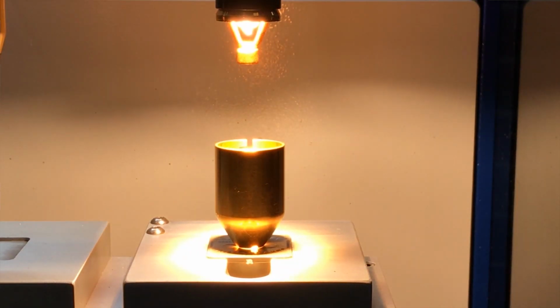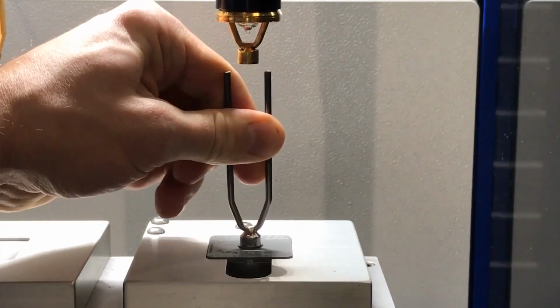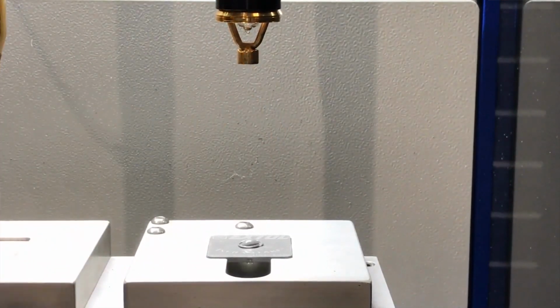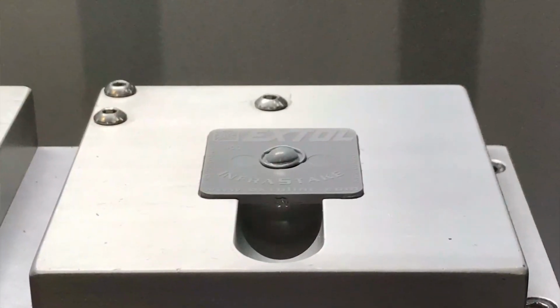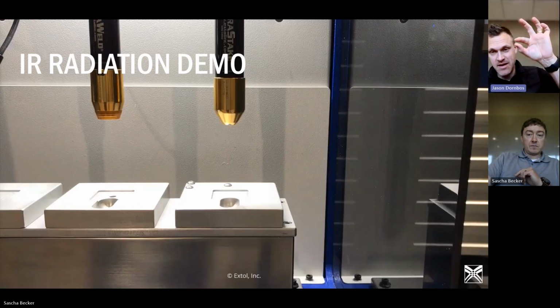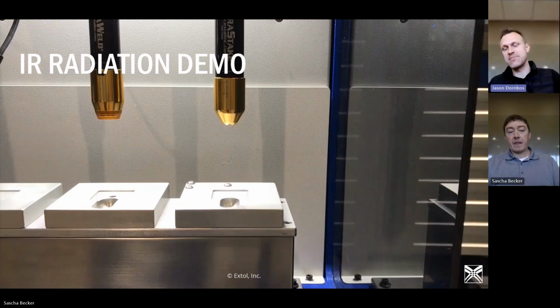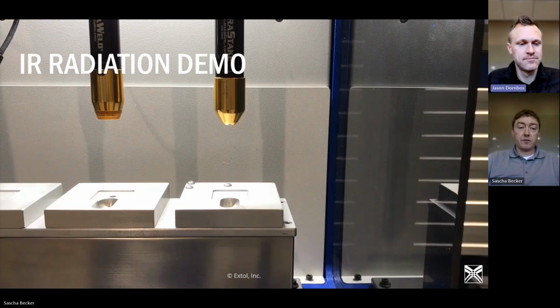What he did is put a sample plaque on there, took that concentrator off the module and just set it over the boss, turn the lamp on, and you can see that boss is soft enough to form by hand. So we created an air gap, plus the punch was not the one that was in the module, it was a different punch, so it wasn't inside the whole heating, so we're not heating that punch up either. So pretty cool video, I think, to show that it is IR radiation.